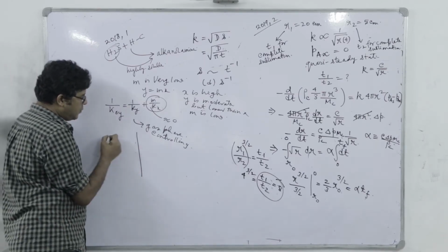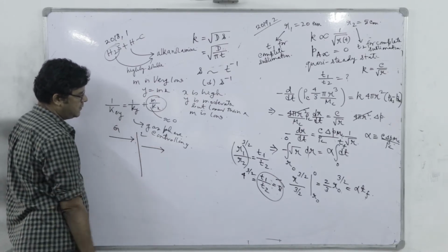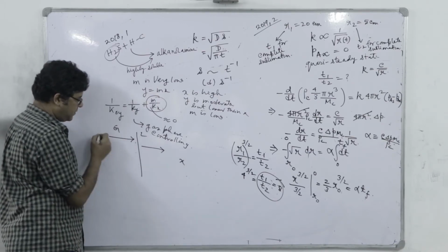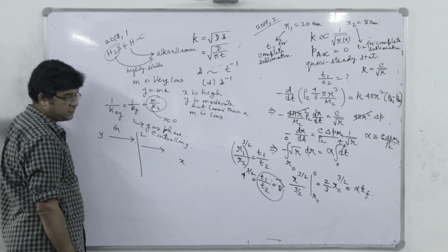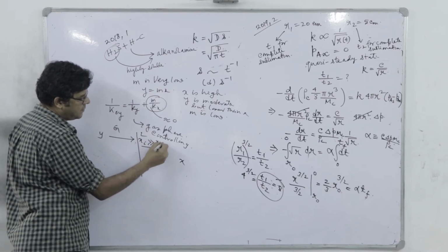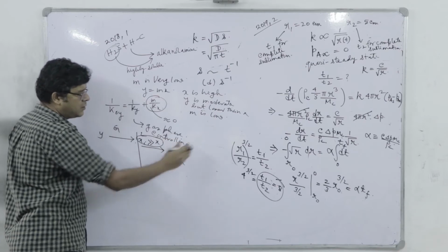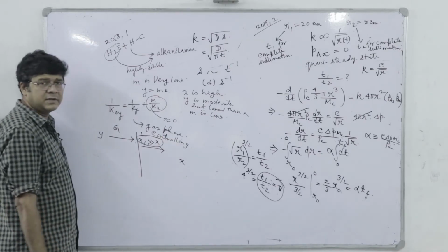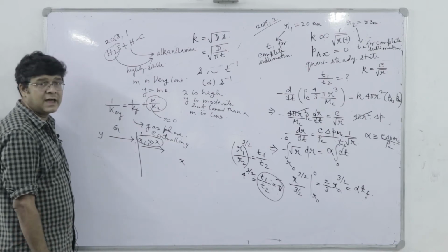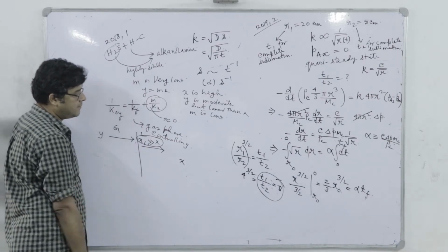See, we have a diffusion in gas phase and diffusion in the liquid phase. So bulk liquid phase, the concentration is X, the bulk gas phase, the concentration is Y. So if I have high Xi in the liquid phase it will automatically diffuse, because at the interface, as the gas component is highly soluble in the liquid, we have a high concentration on the liquid side at the interface.